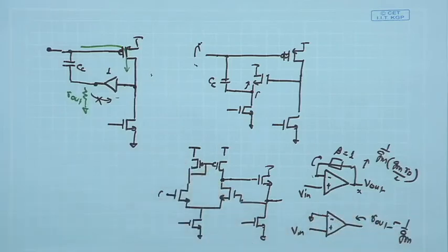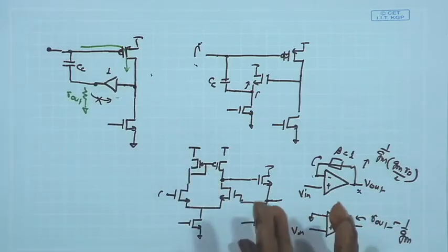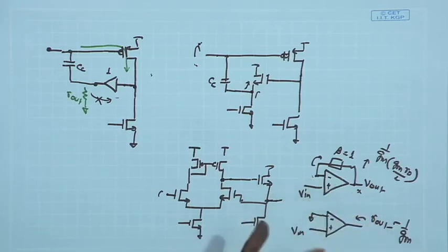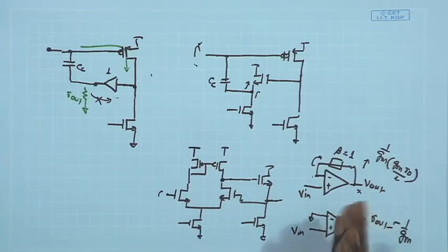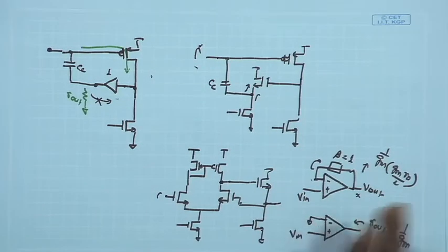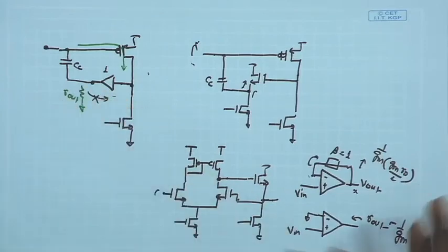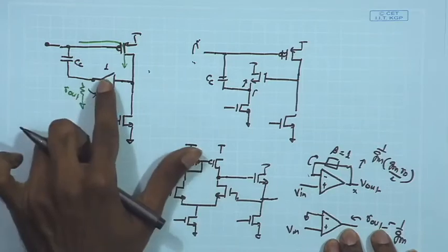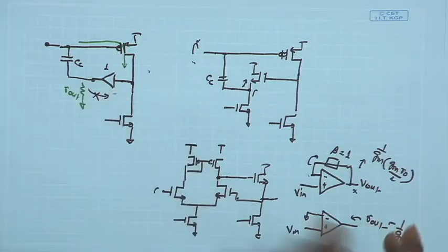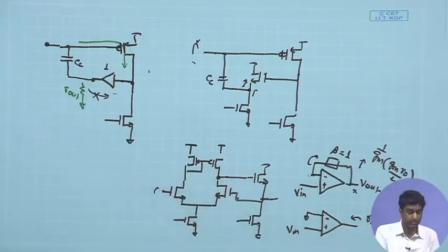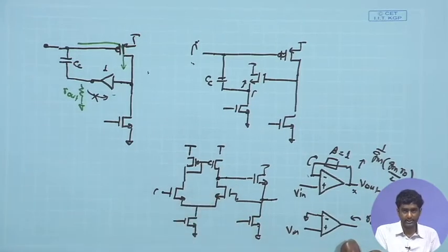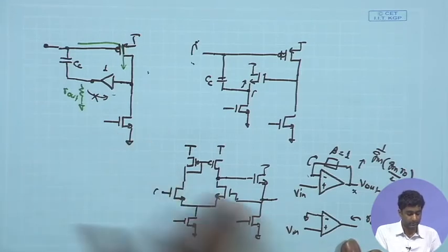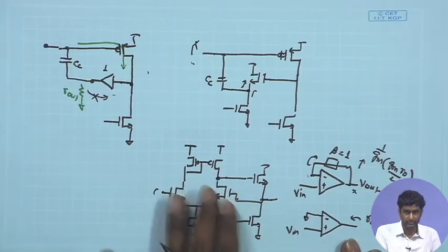For the common mode feedback, we discussed a condition where we are only looking for the DC biasing part. So, even if we make the common mode feedback circuit very slow, if we make the error amplifier of the common mode feedback very low bandwidth, it does not hurt the overall differential response. But here, since this is a part of the differential operation, we need this particular buffer amplifier also to have sufficient bandwidth close to the main amplifier. And one of the good points over here is that we do not need a very precise feedback factor and hence a very high gain for this particular buffer.